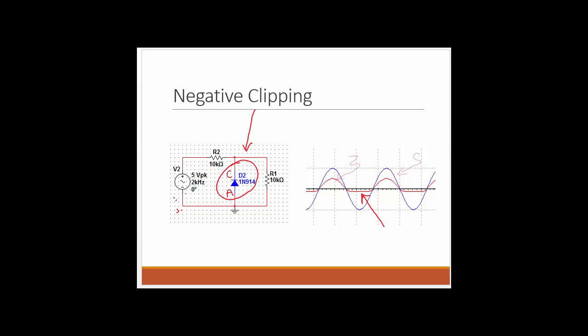Let's say for example, if you require 3 volts of clipping, you can eventually keep increasing the number of diodes that you are putting. So for example, instead of putting a single diode in this branch, I can consider multiple diodes in series. So that will get me, instead of 0.7 volts during the negative clipping, 1.4 volts. If I put 3 diodes, again 3 times 0.7, 2.1 volts. But it is going to give me steps of 0.7 volts if you keep on increasing the number of diodes. But that increases the complexity of the circuit.